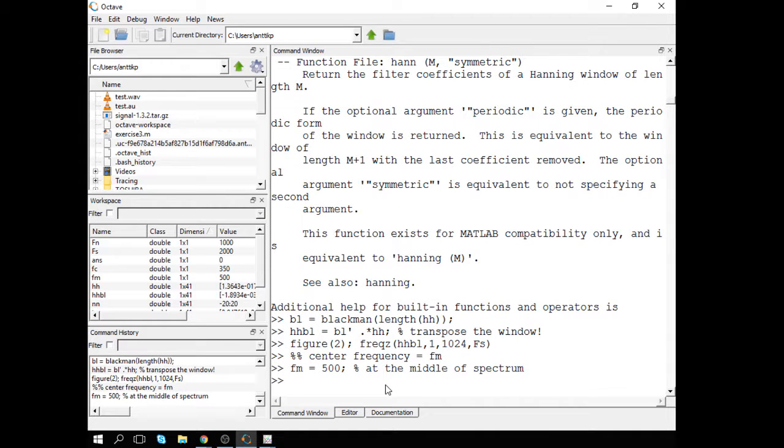So basically then the bandpass filter would be 2 times Hh. I will take the Blackman windowed sinc and modulate with cosine. I try to avoid the sine modulation because sine may have lots of zeros on it. At least at the middle there is 1 zero.